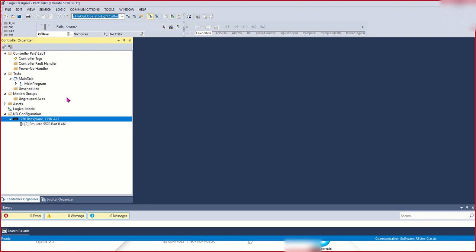You need to download that program without IOs. If you download the program with the field IOs, it will not take it and will give an error message, because the simulator doesn't have any of the hardware input output modules that you have configured.